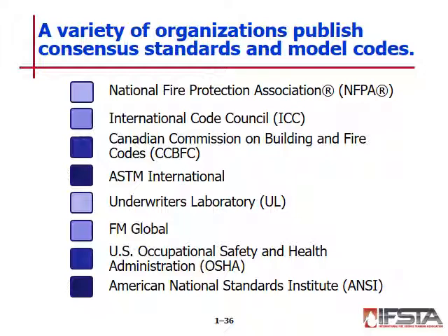Similar to ASTM, we have UL, or Underwriters Laboratories Incorporated. And this is a great resource, and if you haven't already, check out their website because there's a lot of good information on there. Now, UL is an independent, not-for-profit product certification organization that has been testing products and writing standards for safety since 1894. UL annually evaluates thousands of products, components, materials, and systems. UL has developed over 800 standards for safety. Some of these standards relate directly to fire and life safety, such as smoke detectors for fire alarms and dry chemical extinguishers.